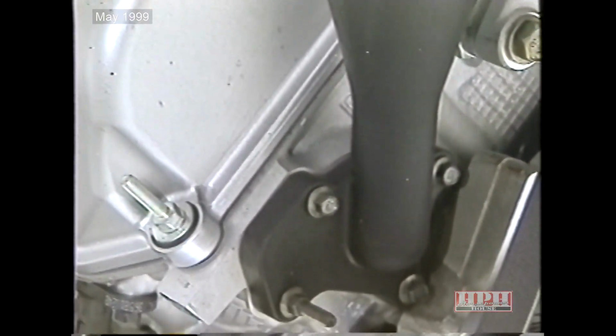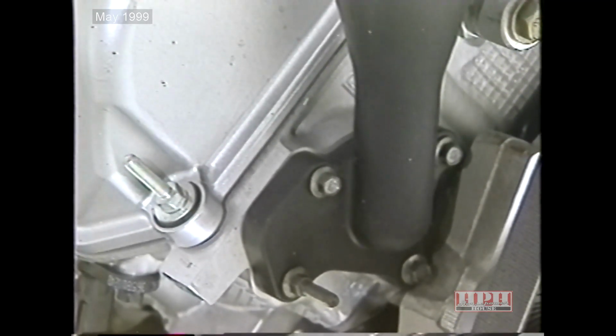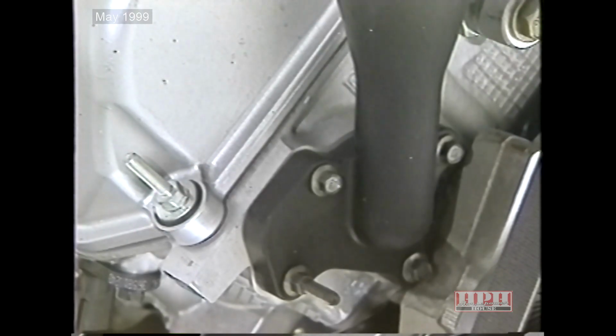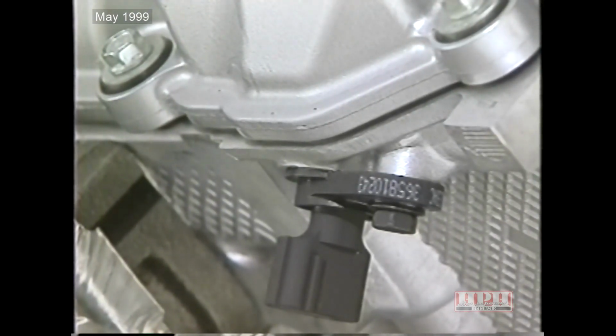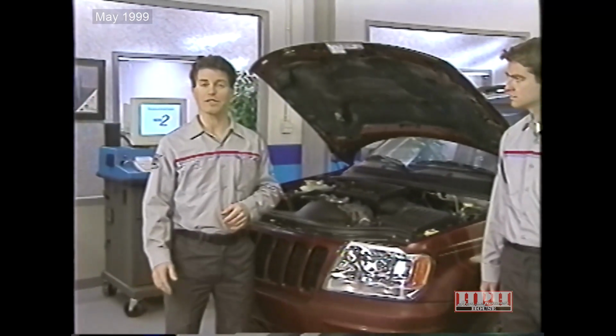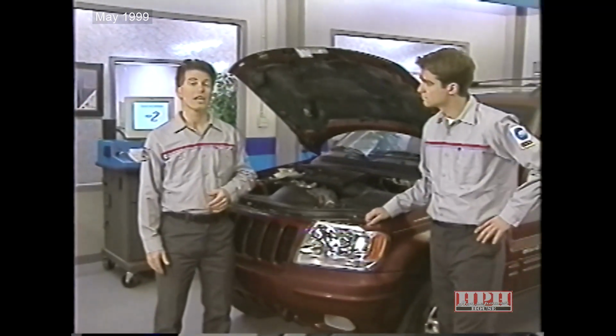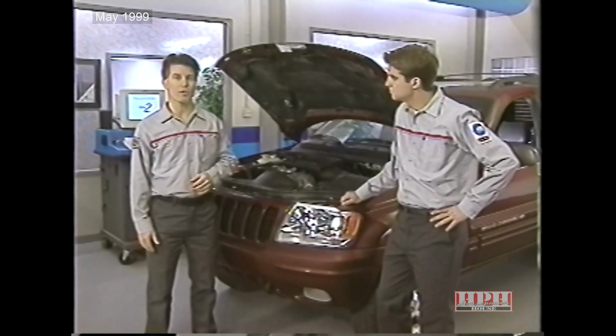Check for leaks around the cylinder head covers. Oil seen here would indicate a weak seal. Inspect for leaks at the oil-filled tube attaching point, at the timing chain guide access plugs, and at the camshaft position sensor seal. Finally, look for the absence of dirt on engine components. Areas on the engine that are cleaner may have been washed clean by dripping oil.